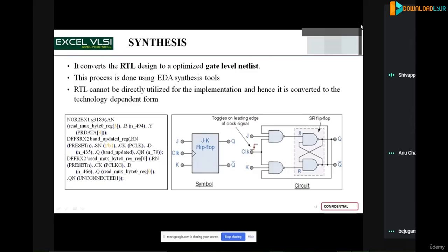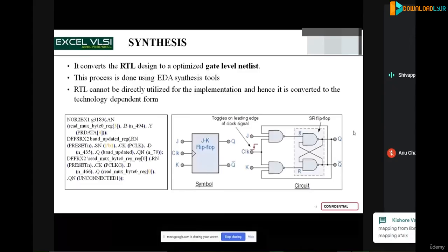Okay. Now the standard cells, if you look at the FPGA flow, how we use them. We are only utilizing the Verilog or VHDL design, and the rest will be taken care of by the Xilinx or Altera tool. For example, the FPGA itself is for a particular technology node. All the logic blocks which are already inside the FPGA are fixed for a particular technology.